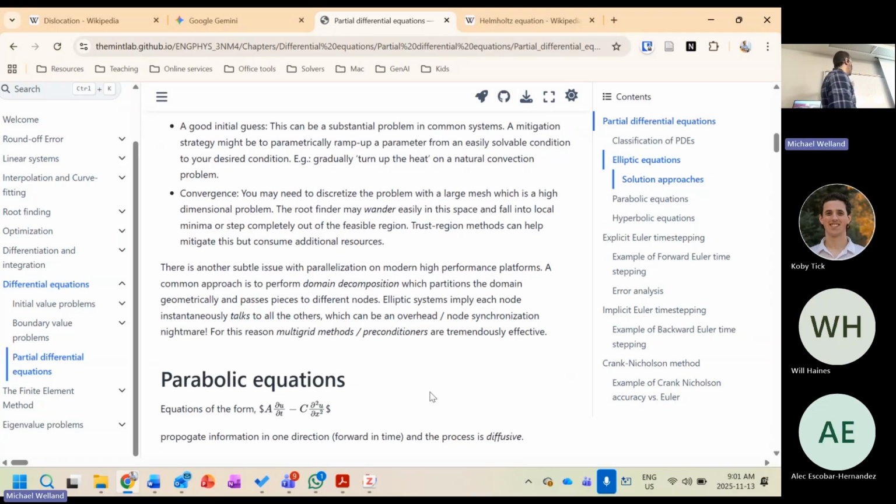Okay, yeah. This whole thing was about this idea of separation onto different computers for high performance computing. This is formally called domain decomposition. Basically what you're doing is you're breaking up your domain into puzzle pieces. There's this whole algorithm called mesh partitioning. It's not really tessellation, it's mesh partitioning. It's a whole field of study, how you do that effectively so that you get different chunks.